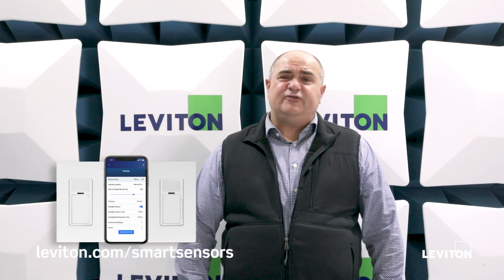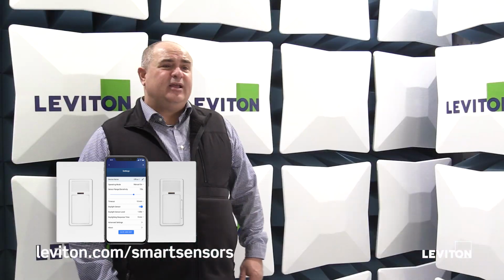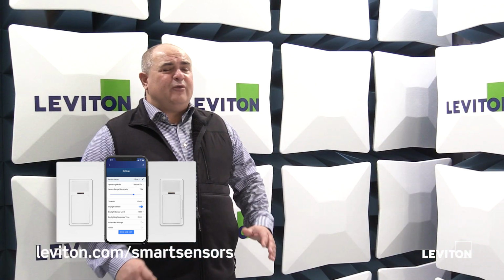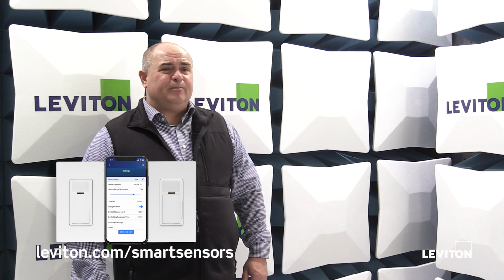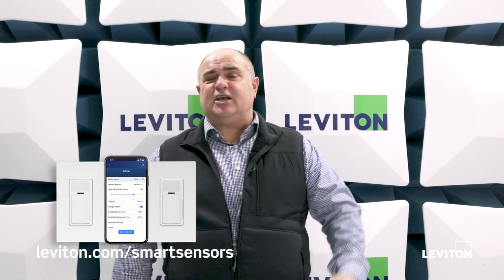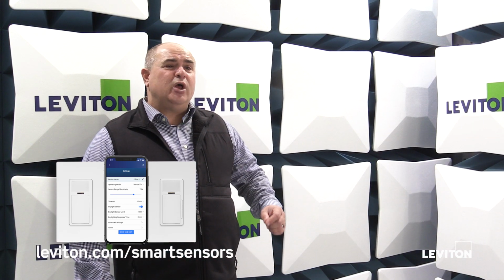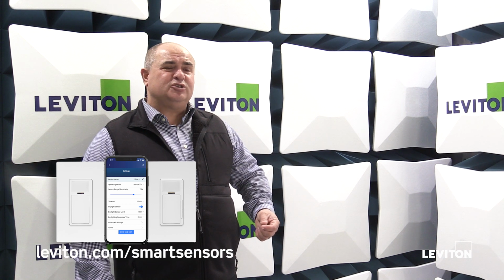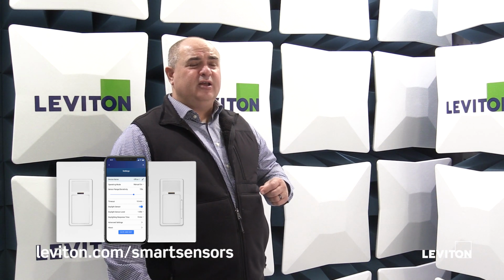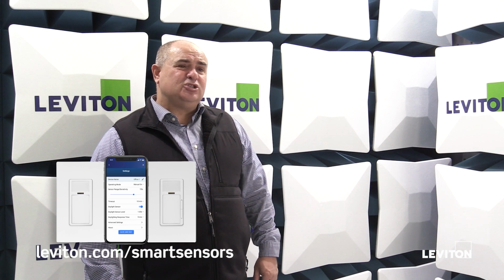What is hold-off technology? Well, the best way I could explain that, let's say you have a room. That room has a beautiful window on the side over here. But you walk into that room in the middle of the day, and that room has plenty of light coming in through that window. Well, what you would do is set up the hold-off technology so that as long as that beautiful natural light is coming in from outside, the sensor will not turn on automatically. So if you have it in occupancy sensor mode and you walk in, it will actually hold off the lighting from turning on as long as the natural light within the space is at a certain level.